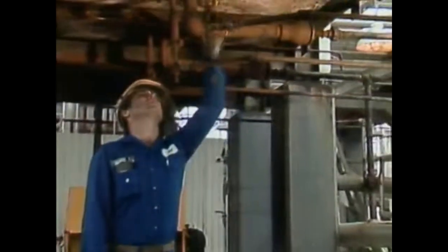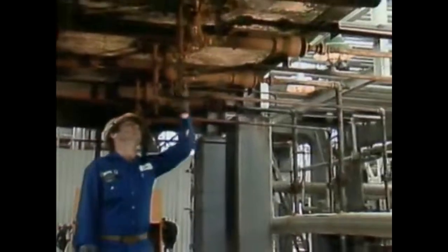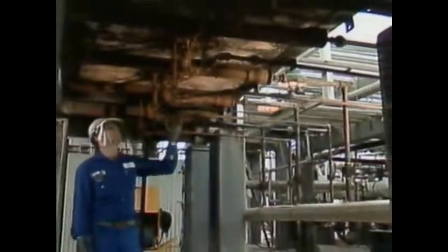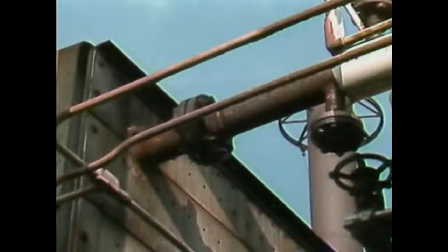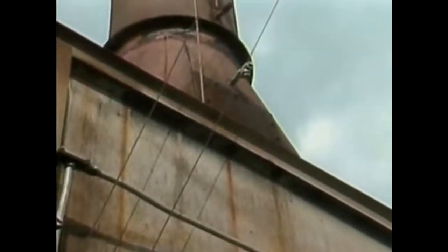Now, an experienced operator can tell a lot about how a furnace is running by simply looking and listening. During your inspection, it's a good idea to check places where air may leak into the furnace. Air leaks can reduce the efficiency of the furnace and give misleading draft and excess air readings. The inside of the furnace should be looked at too, but follow the necessary safety guidelines. To avoid getting burned, wear a face shield and stand to one side when you open the peephole doors.